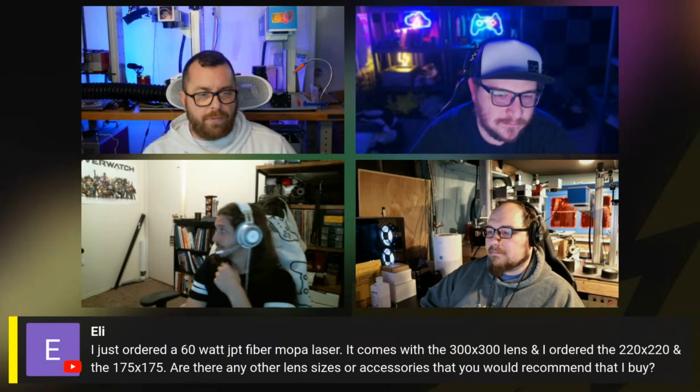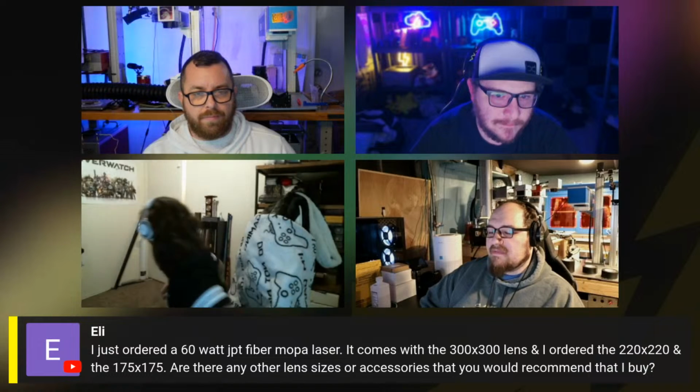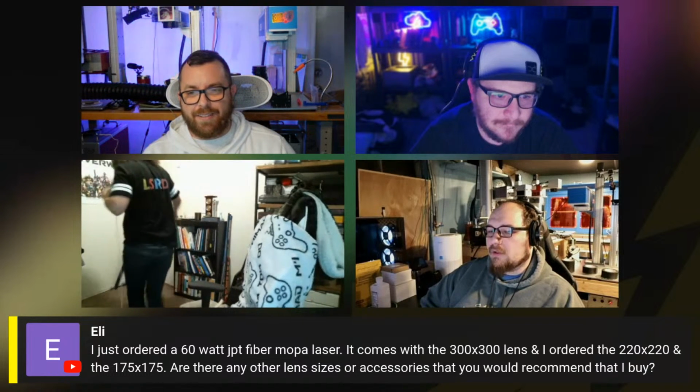All right. Eli said, I ordered a 60-watt JPT fiber MOPA laser. It comes with a 300. I ordered the 220 and the 175. Are there any other lenses or accessories you recommend that I would buy? A 175 is sometimes too big if you're doing stuff like copper. If you're doing copper, get like a 70 or a 110. A 110 I find is a nice all-around lens. Really good. Sometimes 175 just feels too big.